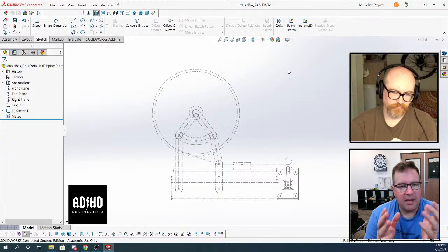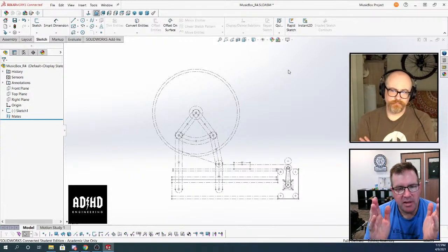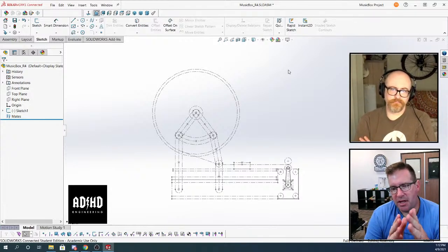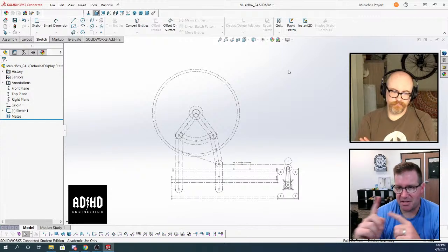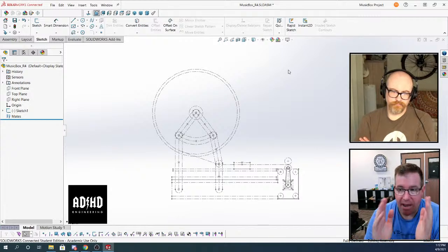But Fusion basically doesn't differentiate between assemblies and parts, the way it blends them. If you're modeling multiple parts in a sub-assembly and they're mixed up in their own different timelines, you'll have this part with a few features, and then a sketch which is in this part, but then you make a new component from it, and now that component is a mess.